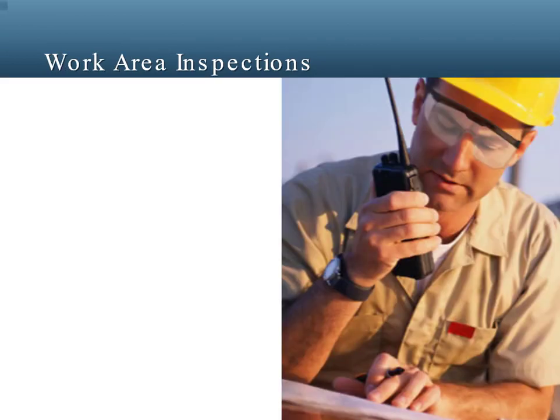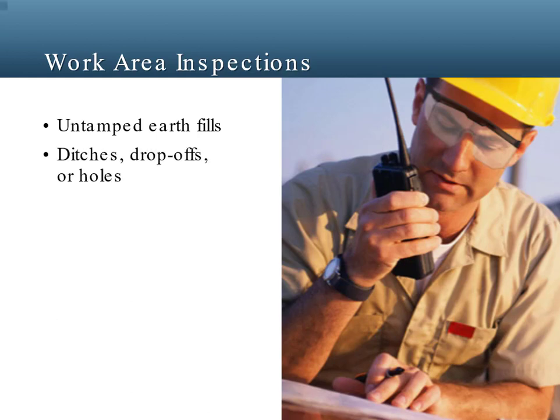After inspecting the equipment, you must inspect the immediate work area for hazards that could result in an accident, such as a fall, tip over, or electrocution. Check for any recent earth fills that may not have been properly compacted. If a tire or stabilizer is placed on the soft earth, the equipment may tip over when the boom is lifted or extended. Keep a safe distance from ditches, drop-offs, or holes to avoid accidentally driving into one, which could cause a tip-over. If you use equipment too close to these areas, the side of a hole or ditch could give way under the weight of a tire or stabilizer.